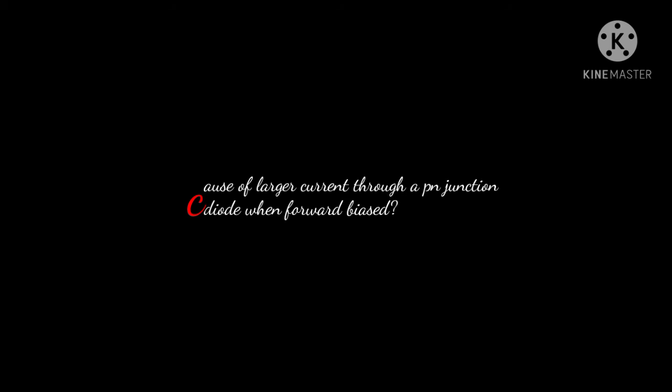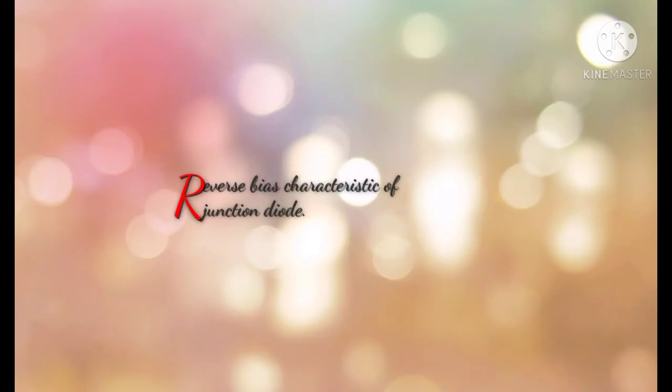Above this knee point, a diode can conduct a very large current. Therefore, to limit this current, resistors are used in series with the diode. This is all about the forward bias characteristic. Now we have to study the reverse bias characteristic of a PN junction diode.